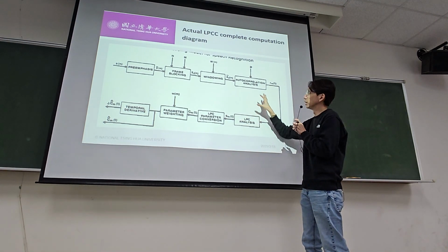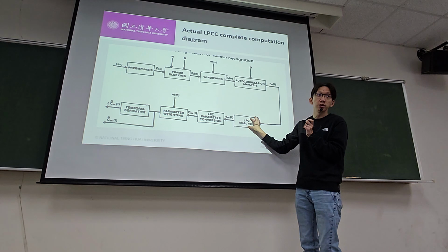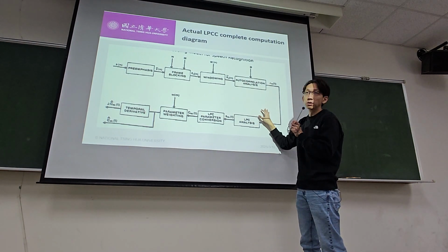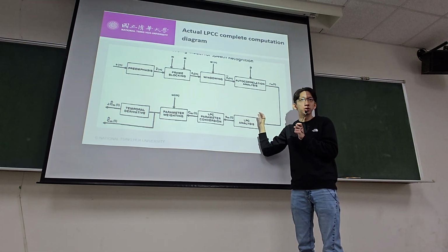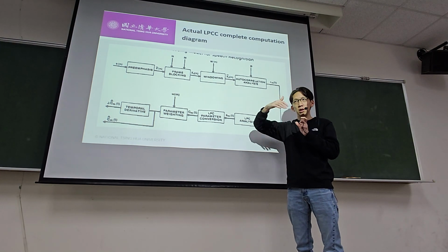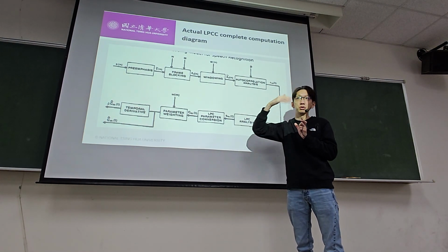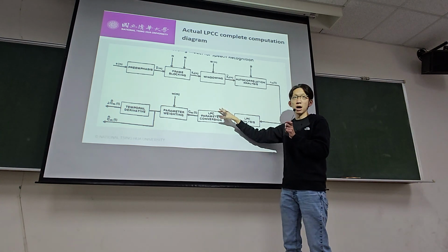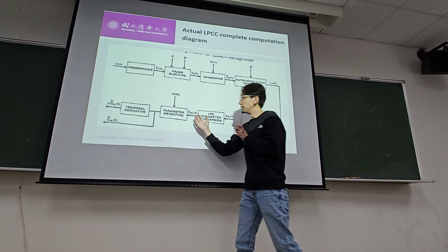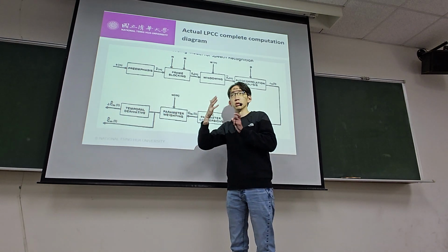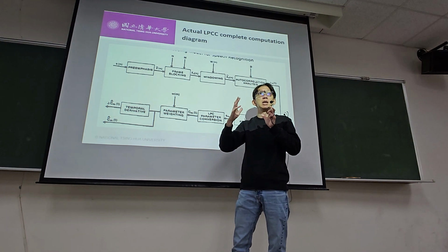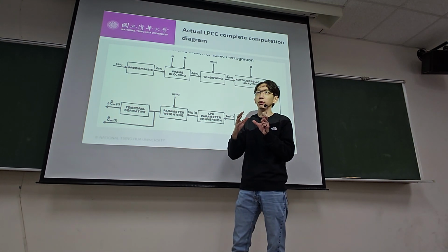The spectral analysis can be carried out simply by taking an FFT and being done. Or you can take a spectral analysis through the view of the linear prediction model, which gives me a set of coefficients that tell me the smooth ups and downs of the spectrum, not those oscillation points. So the LPC model helps me analyze the spectrum in a way that gives filter-like coefficients. Then you do another cepstrum analysis to make sure we're properly lifting out the low time portion, which makes it even cleaner, closer to the actual filter coefficients.